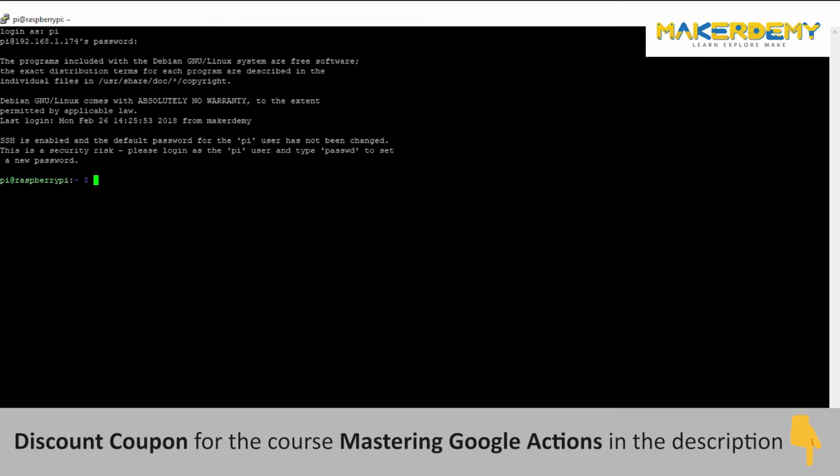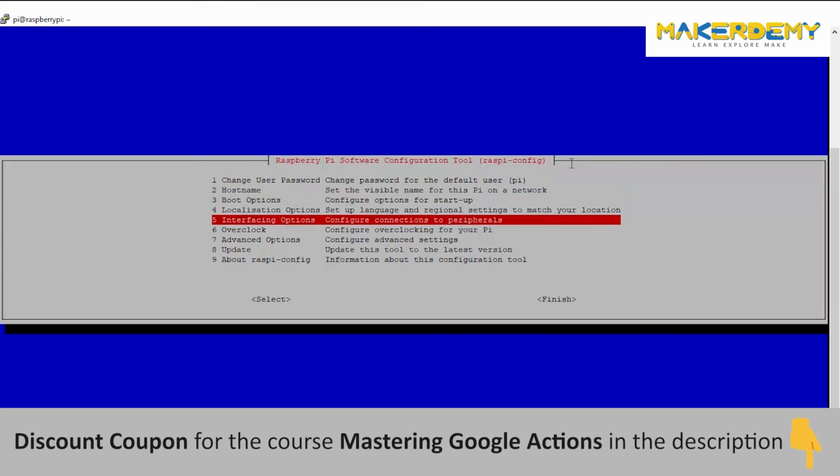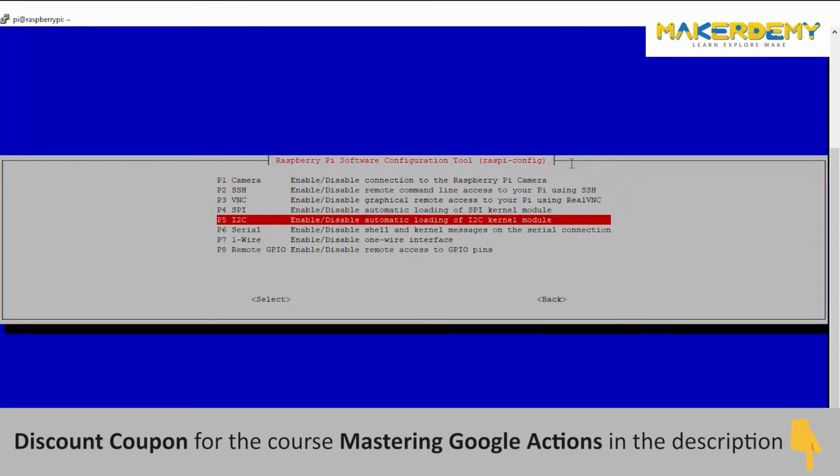Once you are inside the terminal, you need to enable I2C on your machine. Type sudo raspi-config in your terminal and press enter. This will take you to the configuration page. From there, move to the interfacing options and enable I2C.